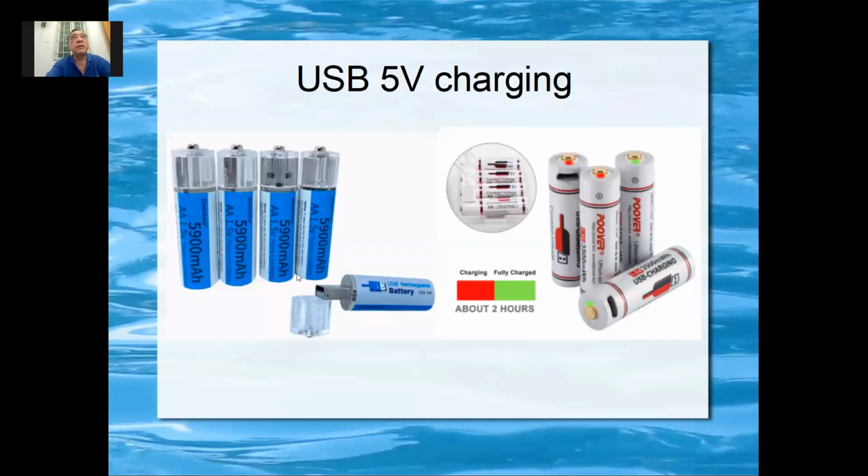Some of these numbers can be fake ones. The reason is when you have such a big connector here, your active chemical is only that small only. You lose a lot of space. So you lose like 30% of the space already. 30% of space is used as a USB connector. So your battery is actually 30% smaller. Whereas the other type, the electronics is on top. So you actually maybe lose 20% of the space for the electronics.